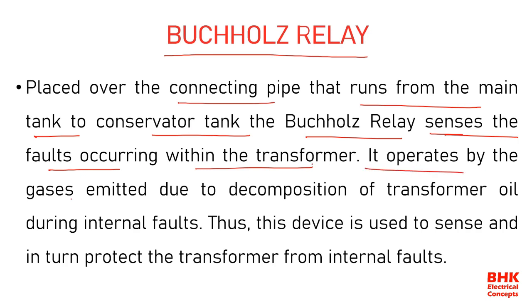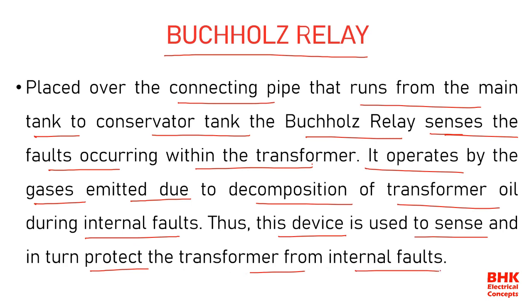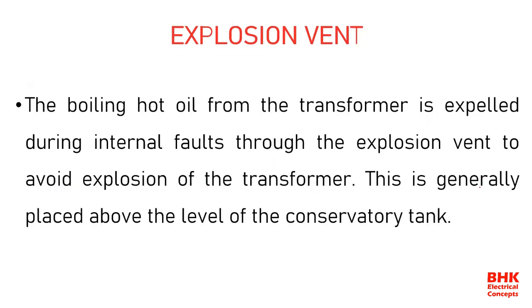It operates by gases emitted due to decomposition of transformer oil during internal faults. This device is used to sense and protect the transformer from internal faults. So the concept of the Buchholz relay is very, very important in the transformer, and the Buchholz relay senses the faults occurring within the transformer, and it operates by the gases emitted due to the decomposition of transformer oil during internal faults.